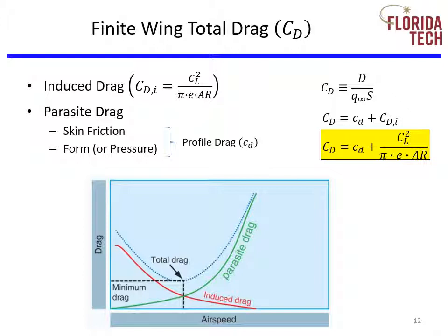Finite wing geometry with wingtips has introduced another form of drag that we called induced drag, or drag due to lift. Skin friction, pressure, and wave drag, if you're supersonic, still exist. In summary, the drag coefficient for a finite wing, denoted as C sub D with capital letters, is written with the following equation. Little cd has the components of the fuselage, the propulsion, and the wings all embedded into the one parameter C sub d with lowercase letters.